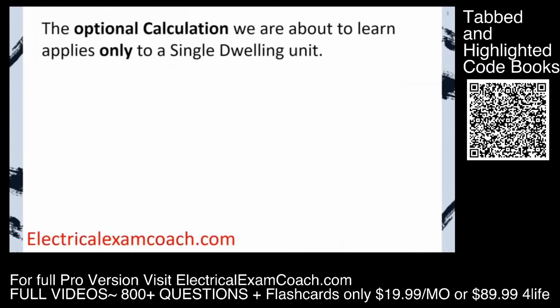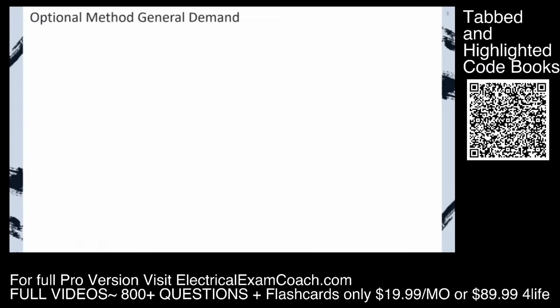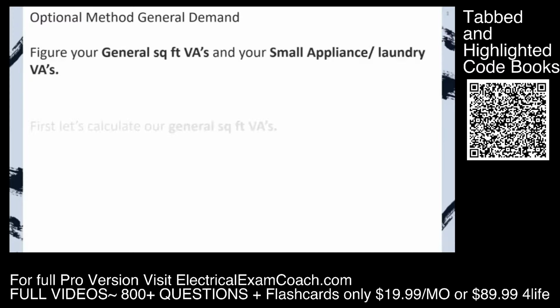The optional calculations that we're about to learn apply only to a single-family dwelling unit. The optional method for a multifamily dwelling unit is very similar to demand factors in a little bit different way, and we'll learn all about that a little bit later in the program. Step 1 with any load calculation, whether standard or optional, is to get our general lighting demand. We're going to do our square foot VAs just like we did before.